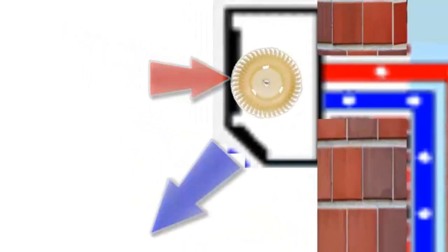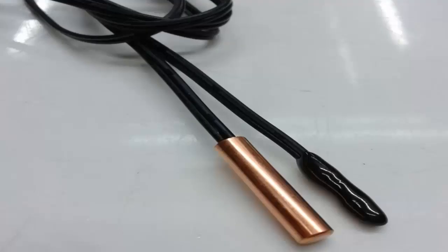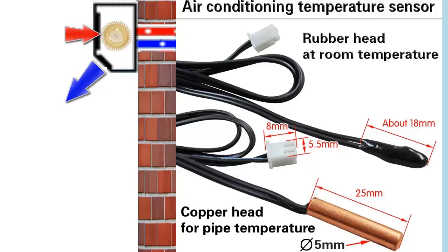3. Sensors. Visually check the connection and position of the temperature sensors. A problem with them can generate incorrect equipment operation, confusing the user with a failure due to lack of refrigerant gas.